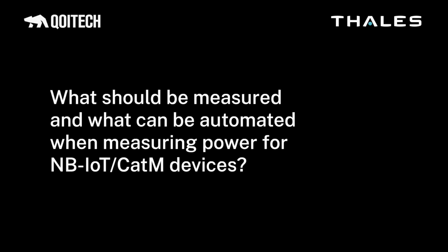The most obvious use case, of course, is the comparison between the measurements you do. Especially if you have taken a look at our previous videos, there was always a problem that different timings cause different values in the overall power consumption. With automation, it's possible to at least have the same timing for your measurements, and therefore the results are comparable. In my daily work, I will use automation and scripting to pass the same scenarios over different types of modules under different conditions, like different mobile operators and different signal strength. Then I can compare it to my previous results and automate everything.